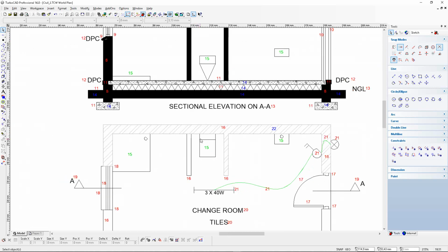Okay, so that is how you firstly will select the area with a polyline to hatch. After you've set up the hatching layer, then you would hatch it, then you will give it a brush pattern, which is the ANSI 32, and then that will be the solution that you get.